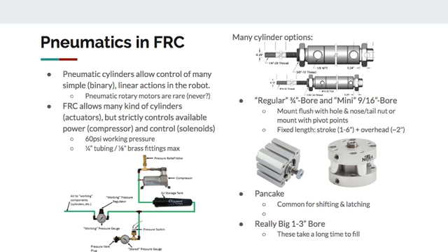Oh, that'd be bad. Well, what if it only works at a higher pressure? So the rule, and I did write it down just for the record, is 60 PSI working pressure and 1/4 inch tubing. When you're calculating how much force you can get from these pistons and how fast they fill up, these are basically the things that matter. Like when we had the unfolding elevator, what if we had accidentally tested it at 80 PSI and it barely worked? Then we got to inspection and had to change it to 60 PSI, we would have been stuck in a hard place.